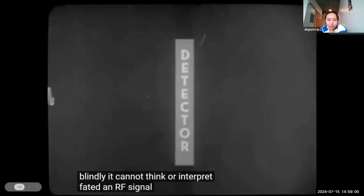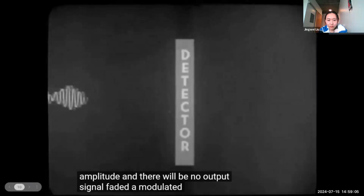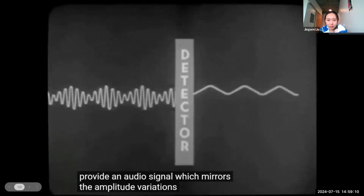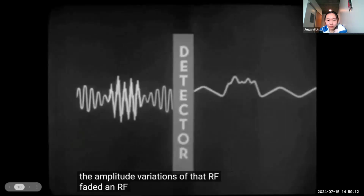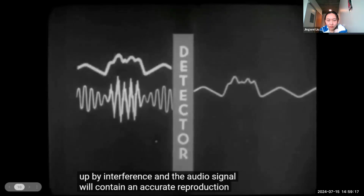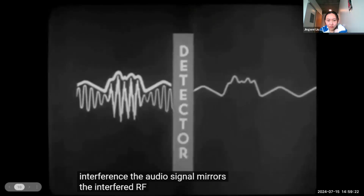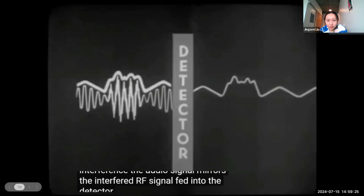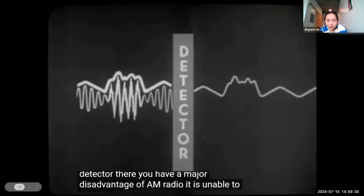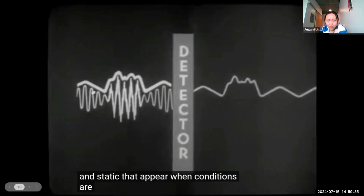Feed it an RF signal with constant amplitude, and there will be no output signal. Feed it a modulated RF, and it will provide an audio signal which mirrors the amplitude variations of that RF. Feed it an RF signal that has been hashed up by interference, and the audio signal will contain an accurate reproduction of that same interference. The audio signal mirrors the interfered RF signal fed into the detector. There you have a major disadvantage of AM radio. It is unable to separate the intelligence from the hash and static that appear when conditions are unfavorable.